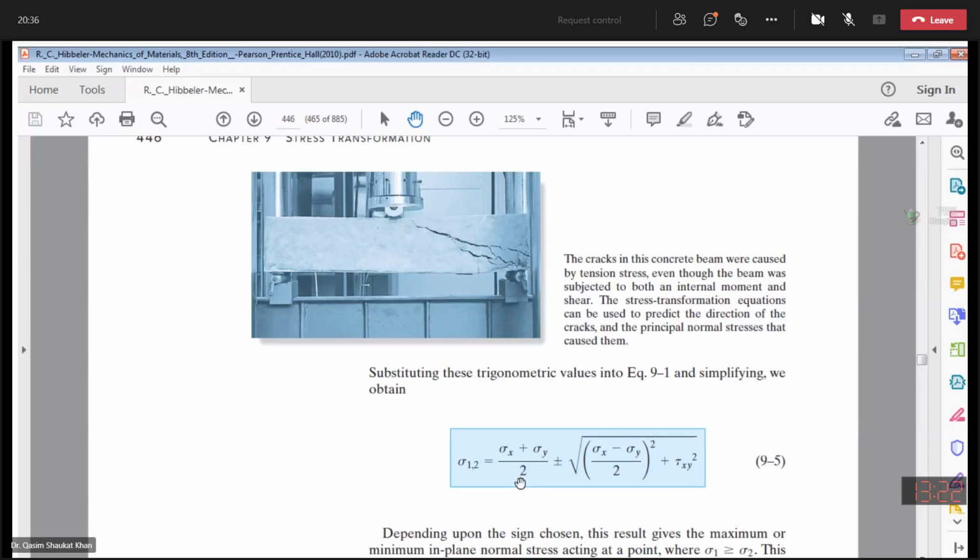In the case of flexural cracks, due to loading, like 2-point or 1-point loading, also called 3-point and 4-point loading, there will be almost vertical flexural cracks originating from the tensile side towards the compression side. They move from bottom to top because the beam is going to sag.